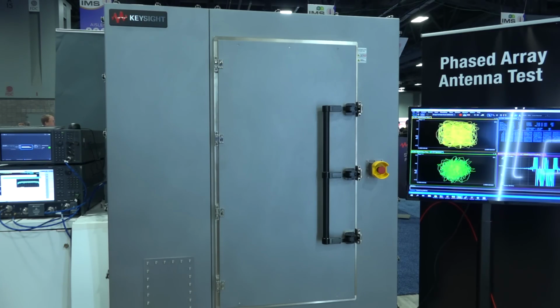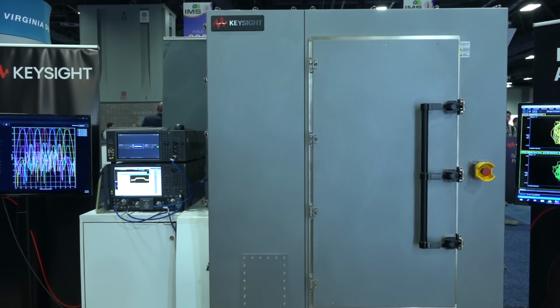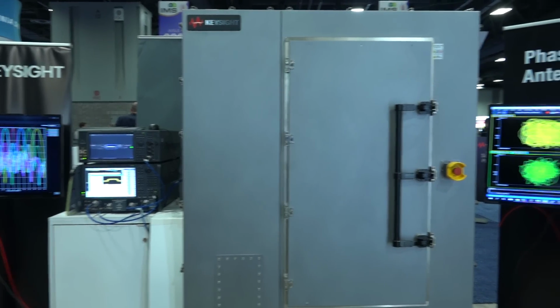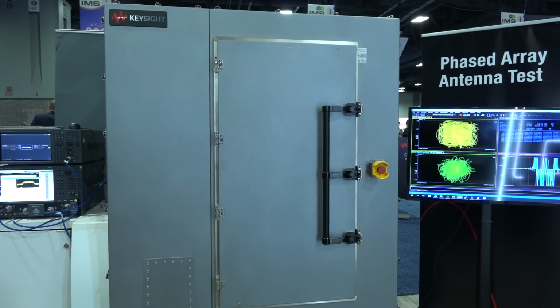This technique is common, but it's extremely helpful in a very compact area to perform tasks at frequencies which would require a very, very large distance to be in the far field of any particular antenna or array that you may have. This is coupled with, of course, their PNAX and VXGs for generating signals. So not only are you, for example, characterizing ERP and various other emissions, but you can also capture waveforms and create constellations directly, showing what the constellation would look like in far field after correction with a reflector. So we'll open up the chamber once this simulation and measurement is done so we can take a look at that. But this is basically competitive to the other boxes we've seen from Rohde & Schwarz.